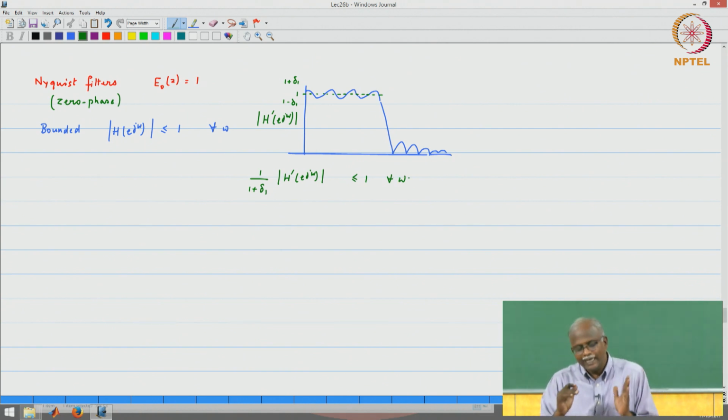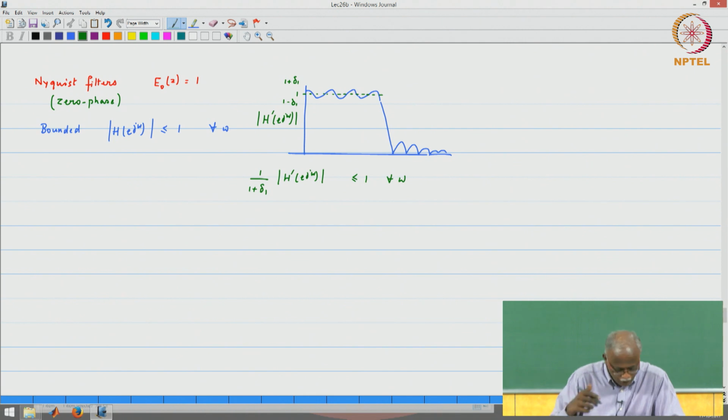So the scaling is a very important element in boundedness, because of the filter response you have basically drawn, you can always make sure that there is an upper bound for it to be satisfied. So when you have filters that have got a well defined frequency response, these are bounded transfer functions. So again this is a useful concept, okay. Now of course a subset of this will be bounded real. I will just write it as R, real coefficient. Then there is another set which is lossless.